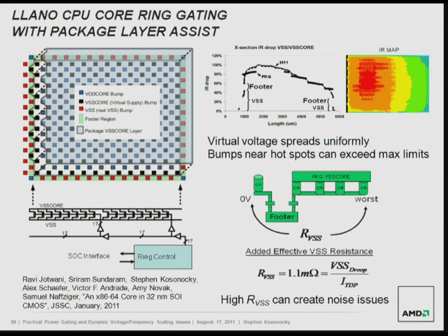And what we do is the normal VDD bumps, VSS bumps, are attached to the package in the middle of the core, and the current actually flows up in through the package, across the sides of the package, or across the sides of that layer there to the edges of the core, then back down into the power gate ring, through the FETs, and then back up through those red bumps there into the package, back into the package and out onto the board. And you see the cross section here, that little green diagram.